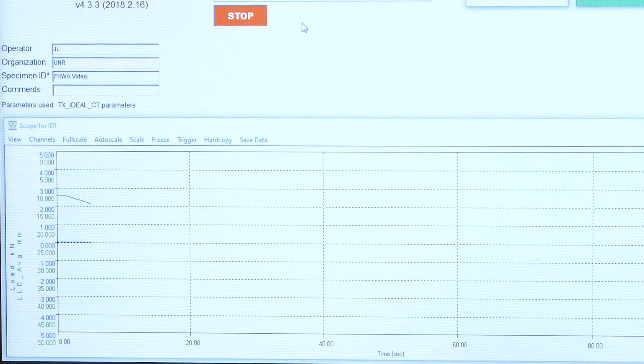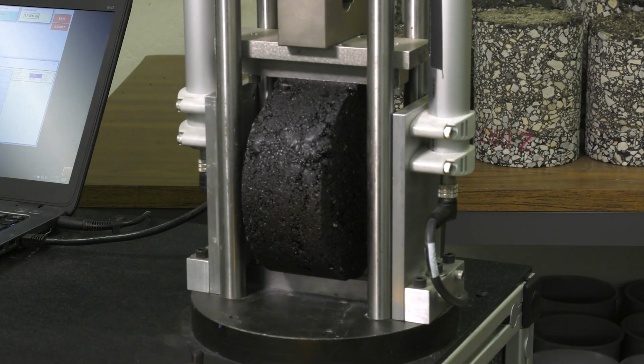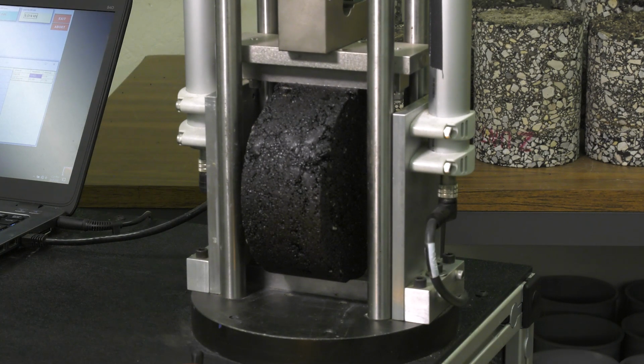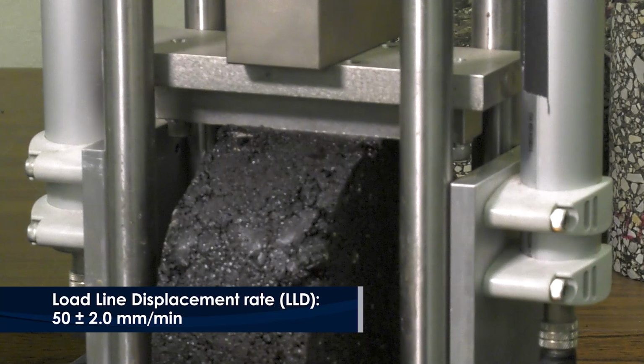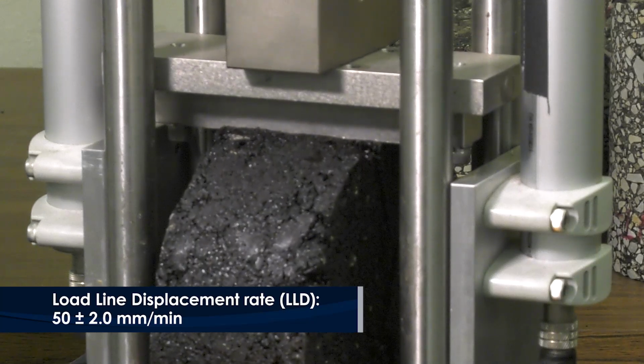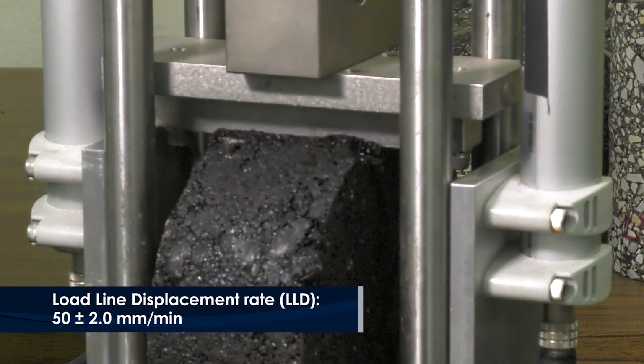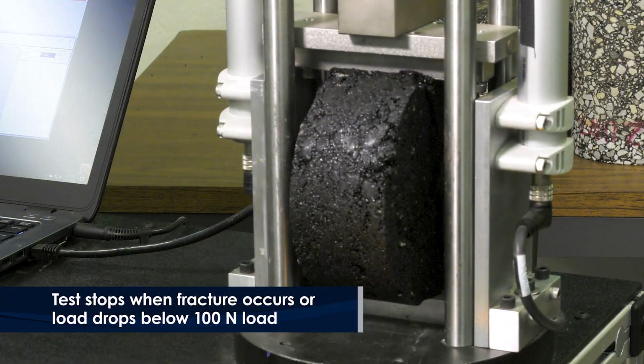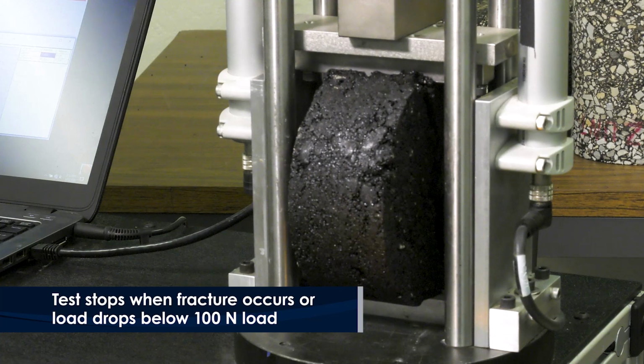Begin the test. The test should be completed within 4 minutes of removing the specimen from the environmental chamber in order to maintain the specimen's specified test temperature. Apply load to the specimen in load line displacement, or LLD, control, at a constant rate of 50 mm per minute. Stop the test when fracture failure occurs or the load drops below 100 newtons.